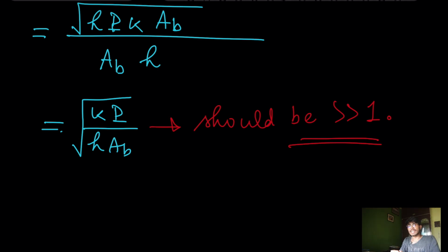So how can you say that? With the change in the medium, this h will be changed, right? This h will be changed. So for water, I think the h will be more, and because of that only the fin will be less effective in water and more effective in air.